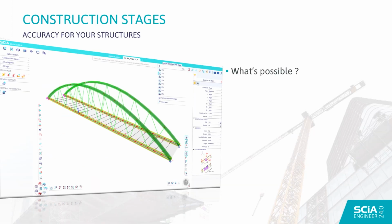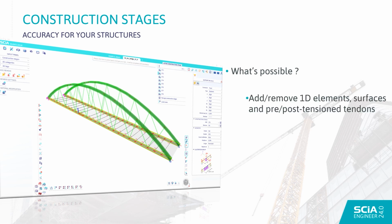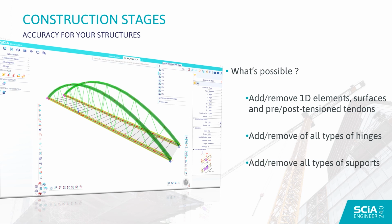So what is now possible with construction stages? It's possible to add and remove not only 1D elements like in the past, but also surfaces, so 2D plates. It's possible to add them and remove them freely. You can also add and remove cables and pre- and post-tension tendons. A new feature is also the possibility to add and remove all types of hinges. And of course, you can add and remove all types of supports.